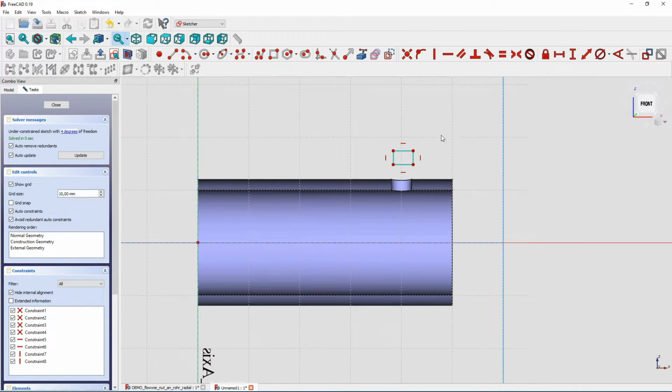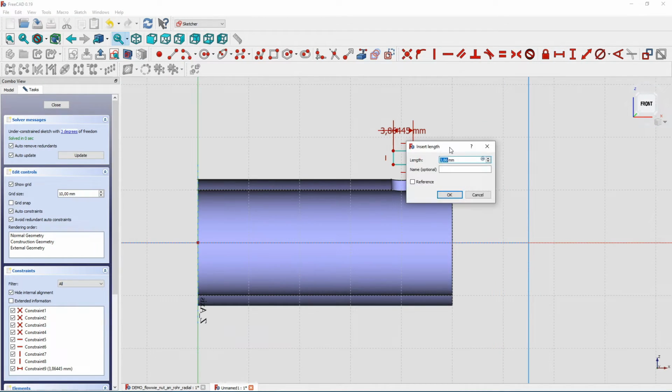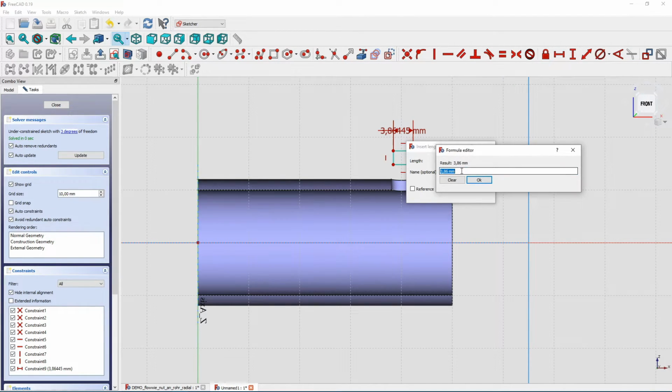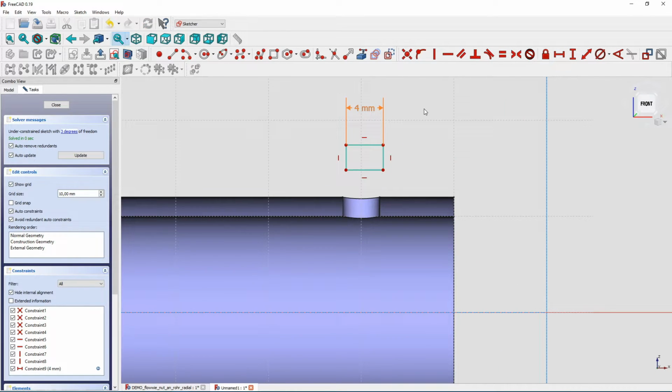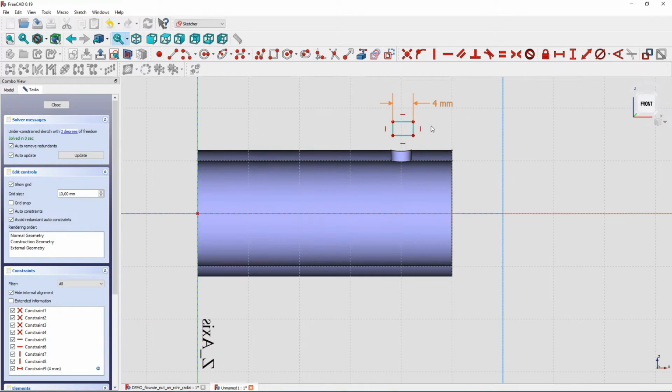And our rectangle here has to have a horizontal distance here. That's not defined here, but this was defined before in our sketch 001. If I had given a good name for it, like a better label, I would not have to select it here, but whatever, I will do it like that. So constraints dot Datum was the name of it. Yes, okay. So this references the Datum that I made in the other sketch.